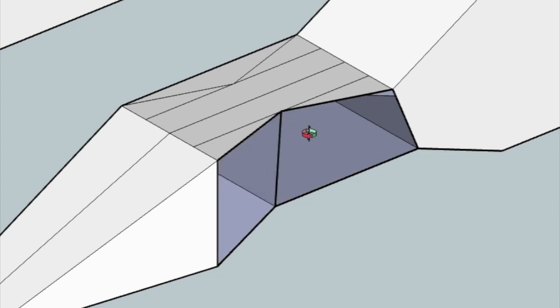Let me back up a little bit. You know what I could have done was I could have gone here. This would work better if I go straight down. You see how I get this blue line? That means I'm on the blue axis. I'm going straight down, and it hits. See, it hits the bottom of this before it gets to this edge. Okay, so I want to do that, and then if I pull over here, oh, I thought that was going to fill in, but it didn't.